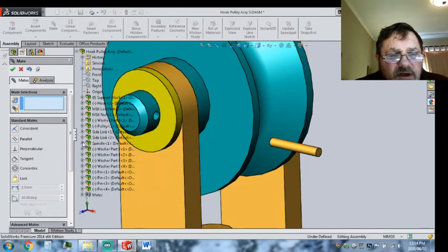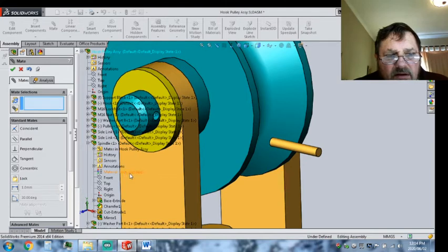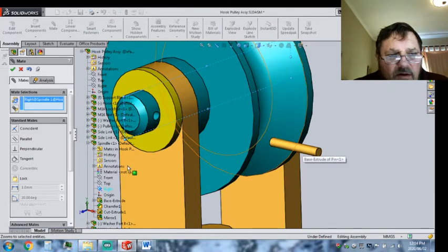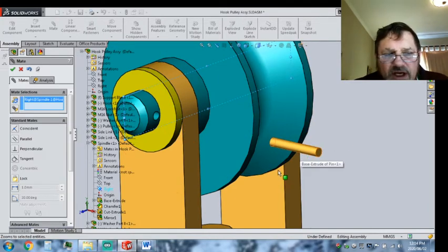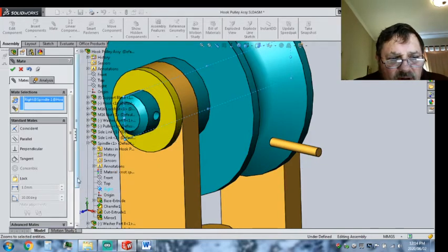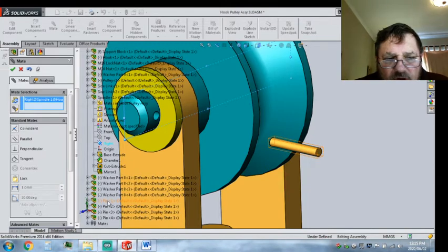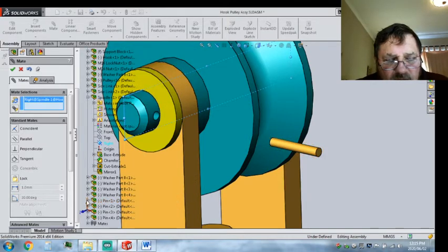spindle. Where's the spindle? So I'm going to do which plane of his? Top, let's go his right plane. I'm going to mate the spindle's right plane with which plane. You see, I need to know which one, the order, which pin this is. But this was pin number 1. I checked it when I did my copying. So you see, if I put the cursor on here, I get the orange wireframe around the part. So I know that's the correct one.